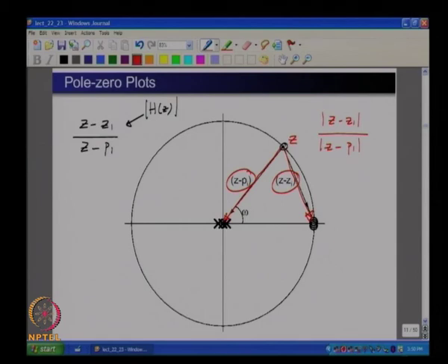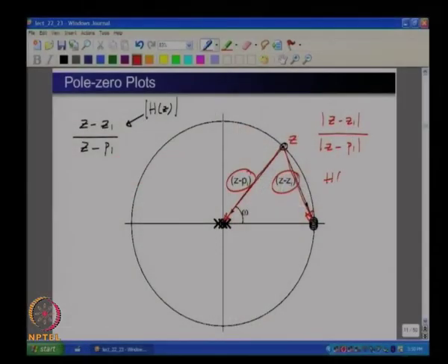correct. And in our situation, we are interested in finding the magnitude of H(z), or the NTF, as we travel along the unit circle, correct. In other words, we are interested in evaluating H(e^jω), alright.